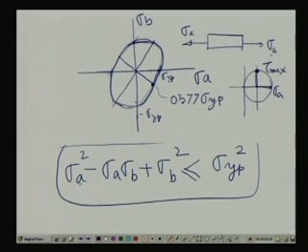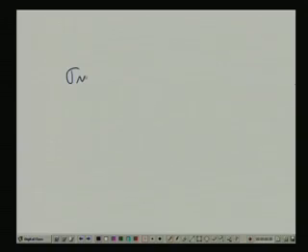Now, let us substitute over here. What is the value of sigma B? That is not coming into the picture. This is sigma A sigma B, and in this criterion this comes out to the yield point square. So, if we substitute, then we get something like that. For a simple tension test, sigma yield point is sigma A by 2, that is we get, can I use a fresh page, we get a situation that sigma yield point square equals 3 tau square.